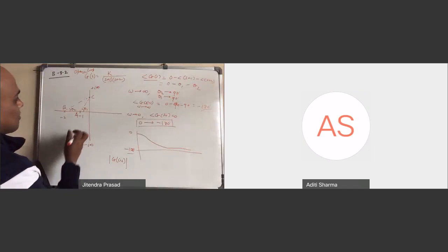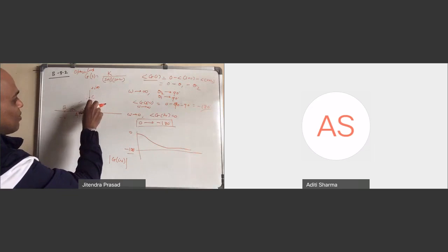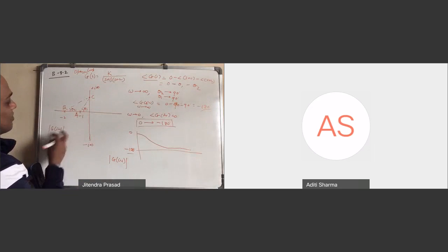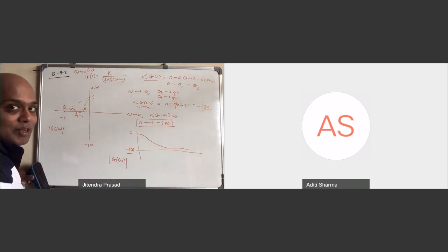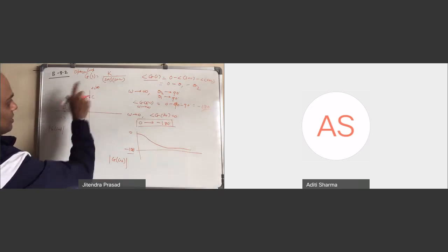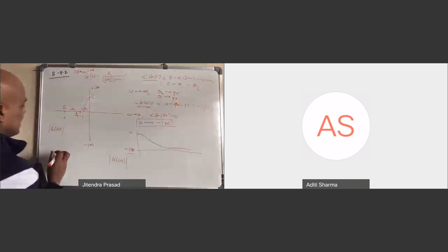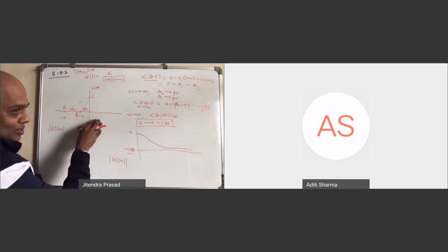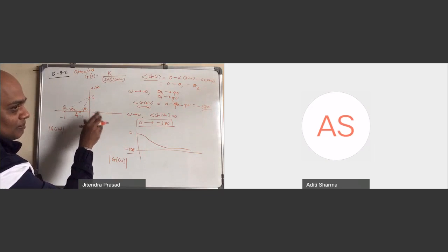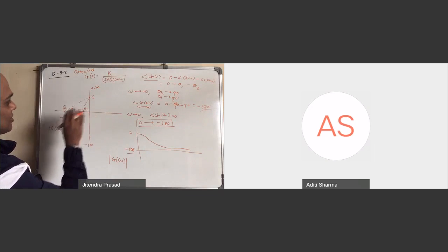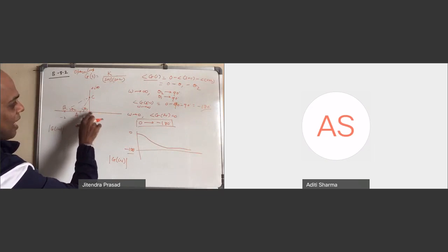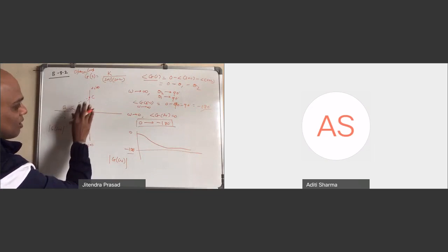Now, what we want is the magnitude, the magnitude of G(iω). That's what we plot, in the Bode diagram and also in the Nyquist diagram. So how do we relate it with the root locus plot or the S plane? Right now we are not actually talking about a root locus plot, where the angle has to satisfy the condition and the magnitude has to be satisfied as k varies. Here not necessarily all angles add up to 180 degrees, it could be any angle, but we are using the same concept you learned during the root locus.